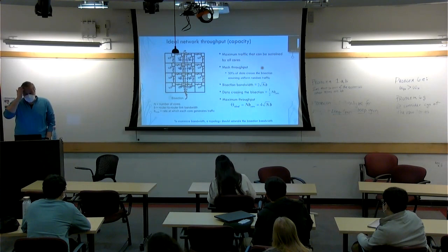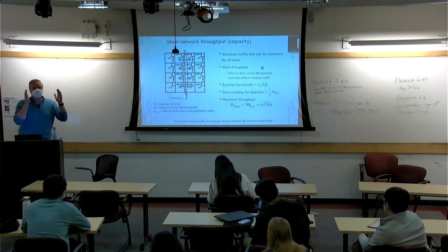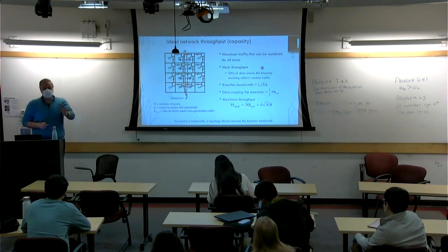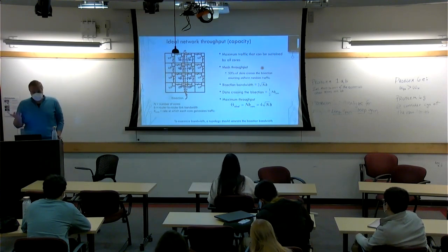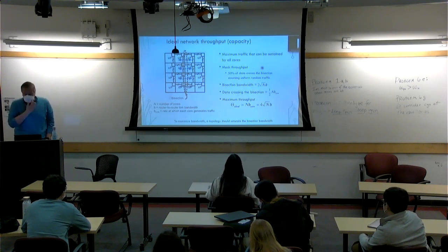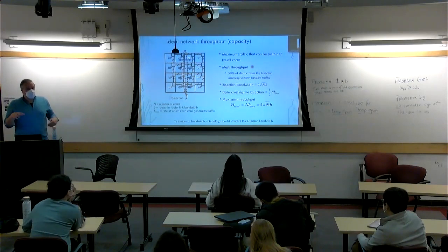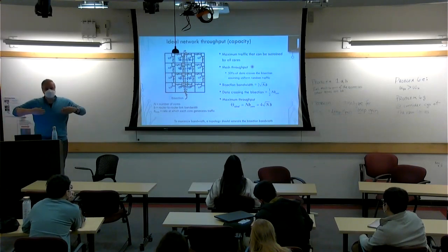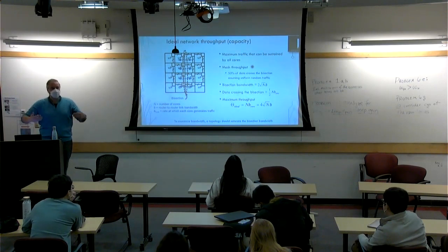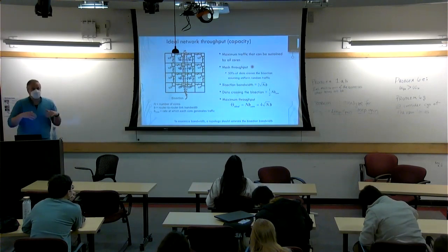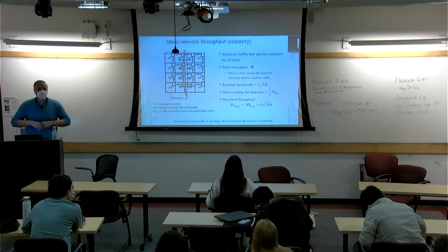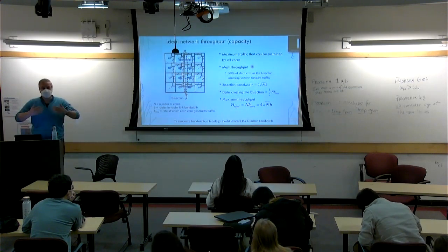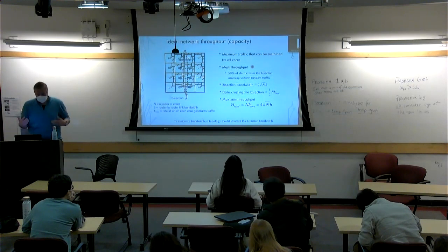Okay, so how do we compute the ideal network throughput? We looked at ideal latency, which is zero load, the best I can do. And now, what's the ideal throughput? Well, this is the maximum traffic at which the cores can inject into the network and still get the work done, meaning there's no overflow dropping of packets. You're actually injecting and stuff is going through.